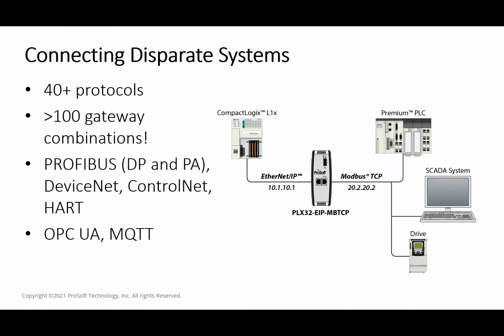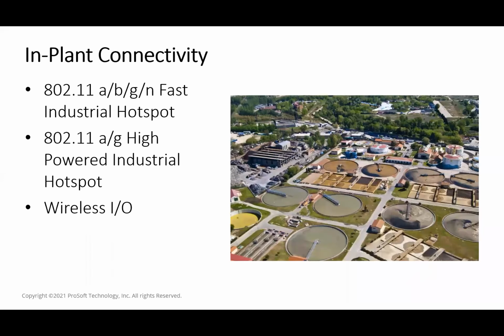With ProSoft, we support over 40 different protocols, giving approximately 100 different combinations, whether it's Ethernet IP to Modbus or Ethernet to Siemens and vice versa, or even communicating with some of the older systems like DeviceNet and ControlNet. We can certainly help you there to connect to these systems and ensure that you can bring the data back. We also support many of the newer protocols like OPC UA and MQTT as well. Again, with the newer protocols, you can actually get what I call plant floor information directly onto the business enterprise.